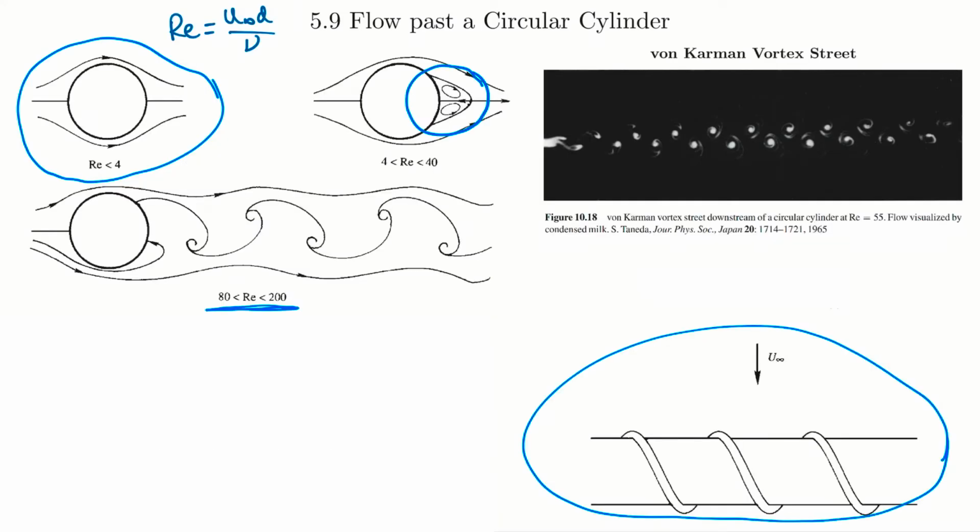Now, the passage of regular vortices causes velocity measurements in the wake to have a dominant periodicity, okay? So the frequency, n, is expressed as a non-dimensional parameter that's known as the Strouhal number, which I've shown here. And some experiments have shown that for a circular cylinder, the value of S remains close to 0.21 for a large range of Reynolds numbers.